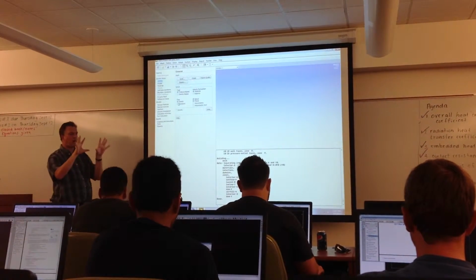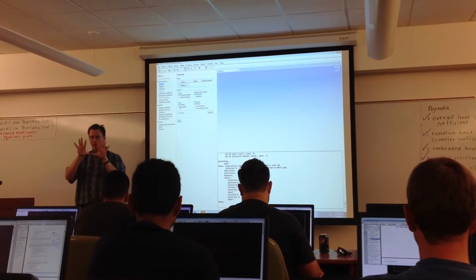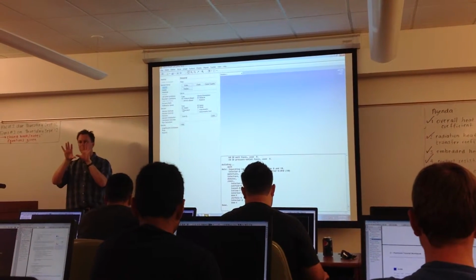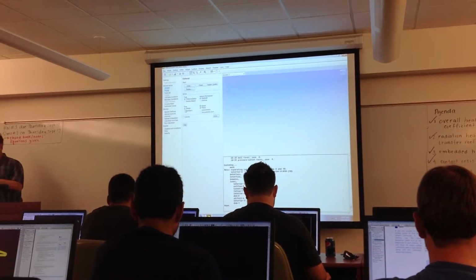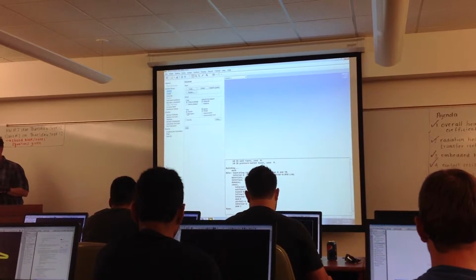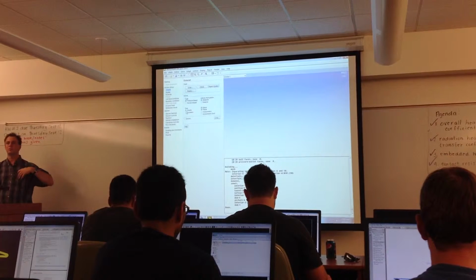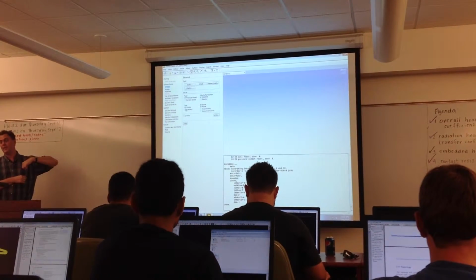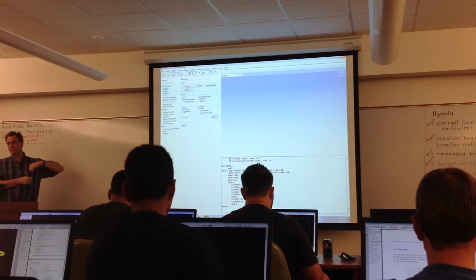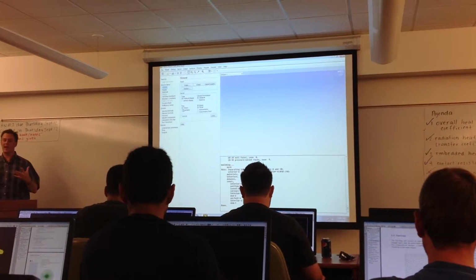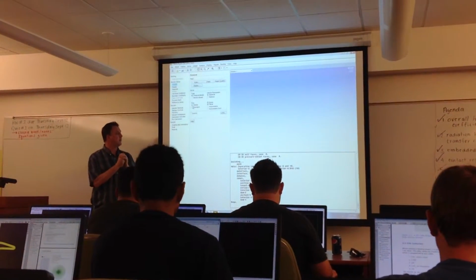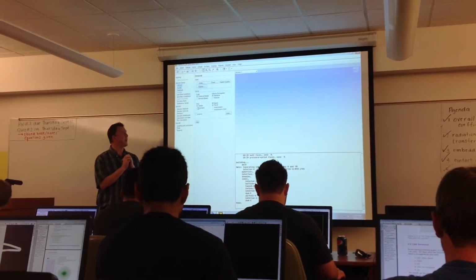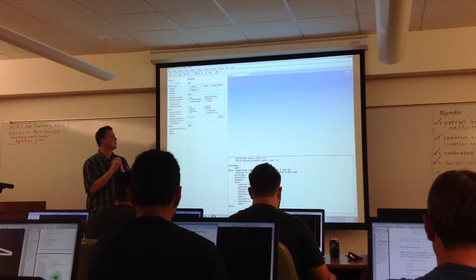The algorithm is going to try to obtain a converged steady flow solution. It's not going to be able to do it. That's what we're going to find out. It's going to have unsteadiness that the fluid is going to be unable to eliminate. And that's just because it's reality. The numerics can't really defeat physical reality. It's a strongly unsteady flow solution.